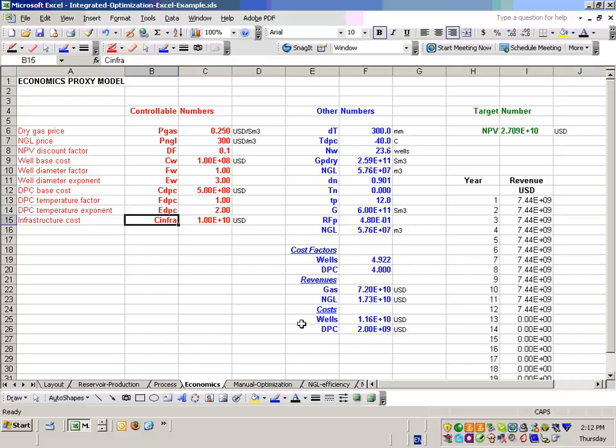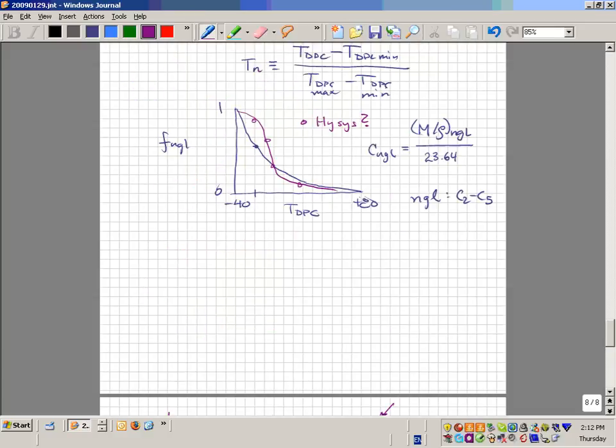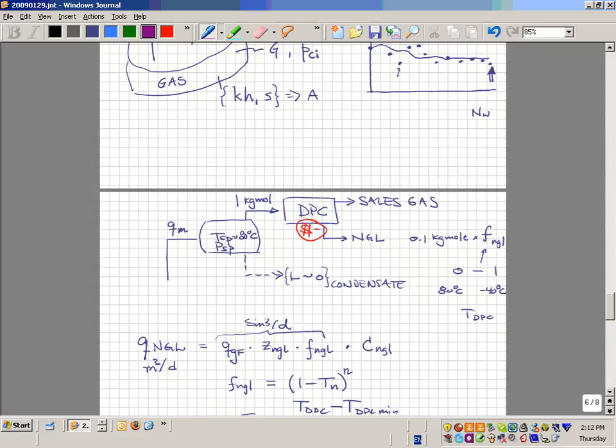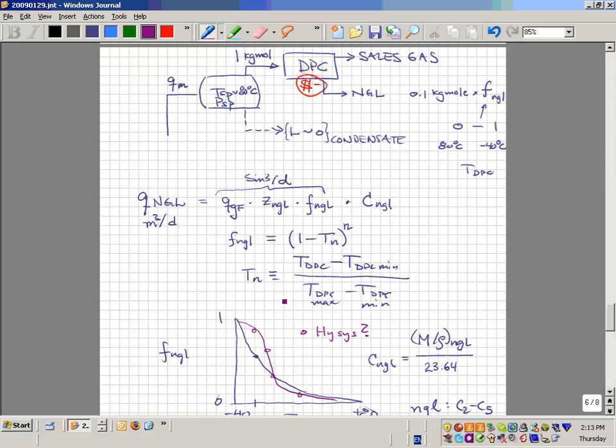Is it necessary, like you said last semester, to take the C1 out of the stream of the engine? Is it a demethanizer process? I've tried to make this surface processing as simple as possible. We're not doing flash calculations. We don't know how much methane there is. But it's a demethanizer process where we should take out the C1 before we go to the next step.